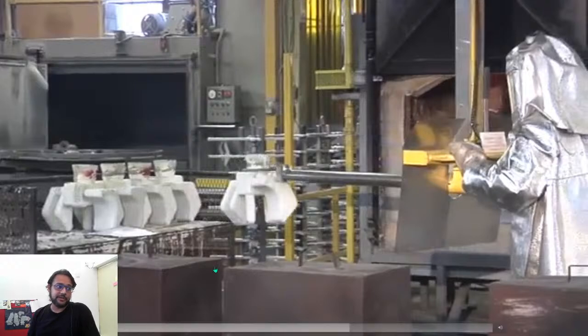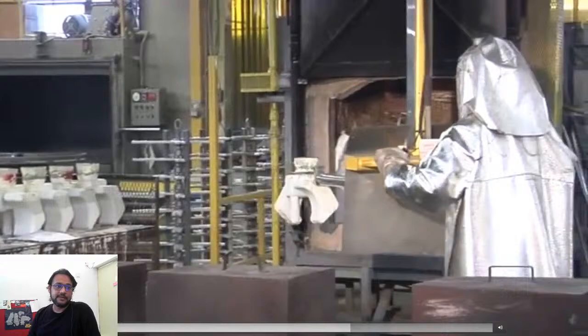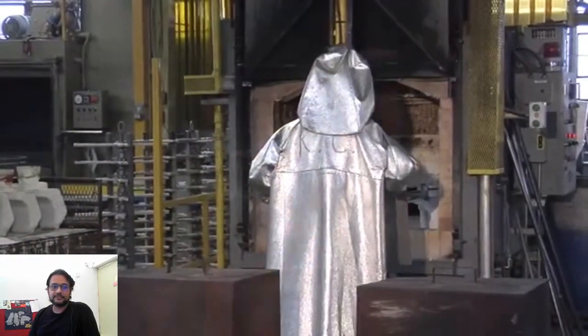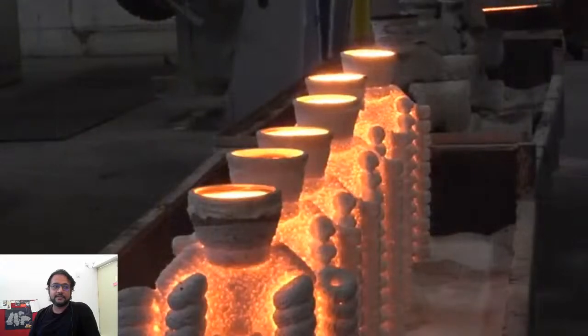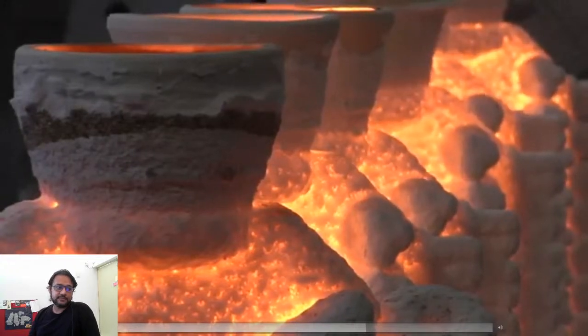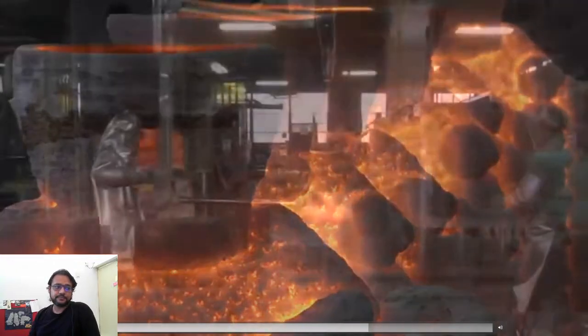It is just a cavity made out of this ceramic material. When the shells are scheduled to be poured, they are reheated to approximately 1700 degrees to further condition and strengthen the ceramic shell. This is now able to withstand the thermal stress they must endure during the next stage.